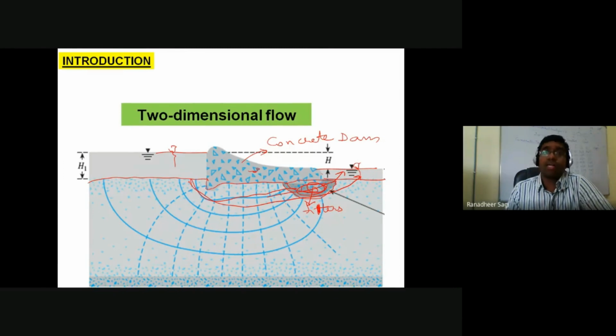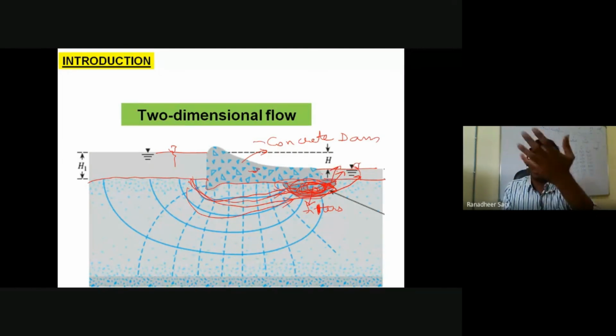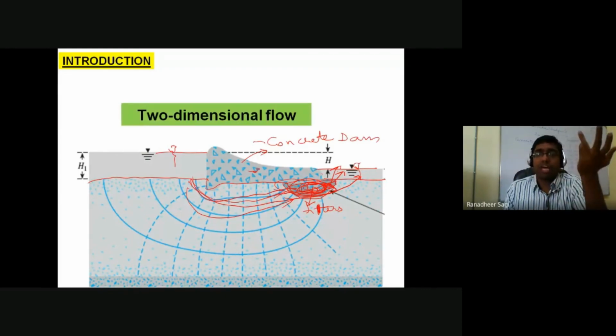So in order to avoid that kind of problem, and also in order to minimize the seepage pressure being developed at the bottom of the cross section of the structure, we try to provide what is called a proper filter design. We go for a proper filter design so that whatever water wants to move from upstream to downstream because of the seepage will flow into this particular drainage path, and from this drainage path water can be collected easily, or easily diverted onto the downstream without any kind of failure in the ground, or rather without any kind of failure getting transferred onto your structure.